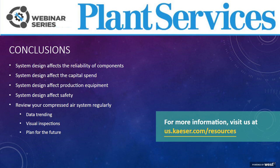You can hear it. Sometimes you can also see it if you're looking at data. We didn't really talk about this in this webinar, but if you're looking at a key performance index of compressed air, which would be specific power, anything under 20, 22 kilowatt per 100 CFM would be a fairly decent specific power, depending on what operating pressure you have. But in cases where compressors are cycling quite a bit, you're going to be over that 20, 22 kilowatt per 100 CFM threshold. Neil, I'd like to add one more thing in there.